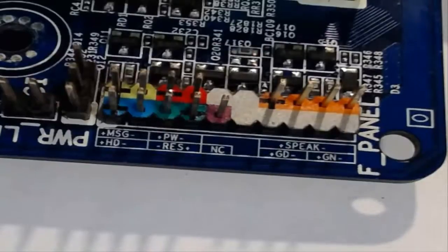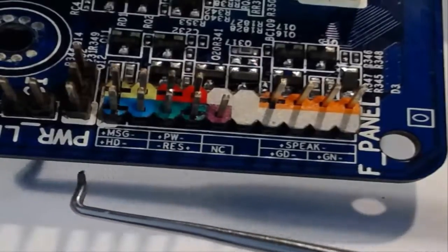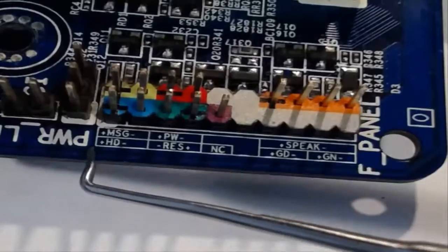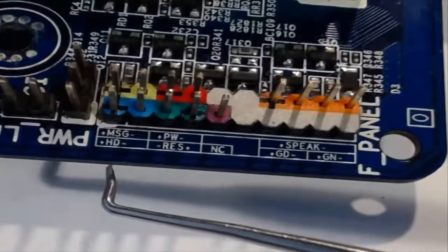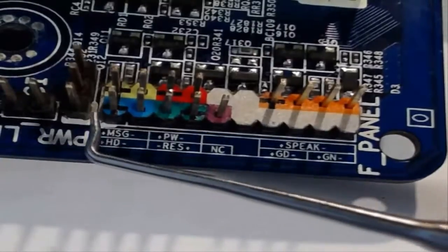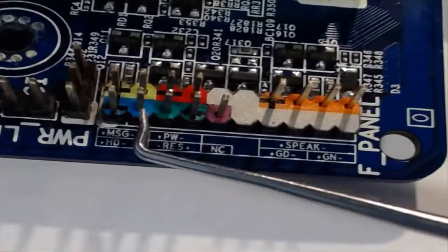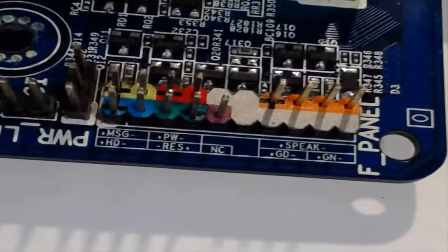It's very difficult. This is probably the most difficult part of building a PC. And the last one there is the hard drive LED indicator light, and it's down on the motherboard as HD, and the plus sign is before the H and the minus is after the D, and it corresponds to the blue one here, and there's a plus sign and no sign, which is the minus. So we'll just connect them now.